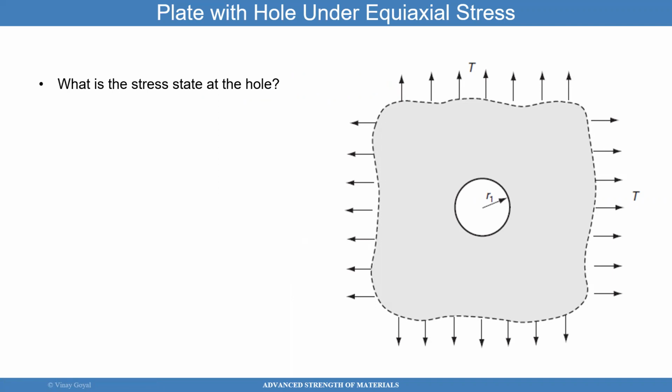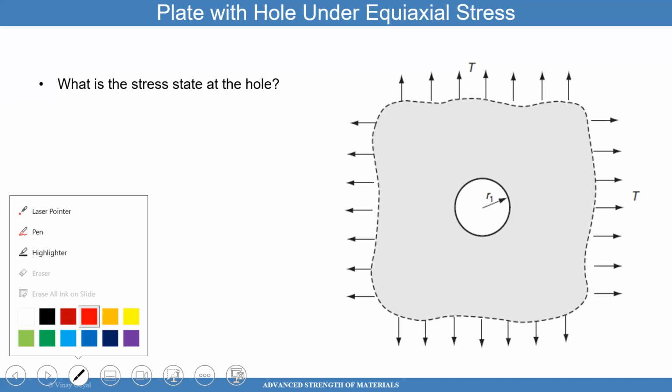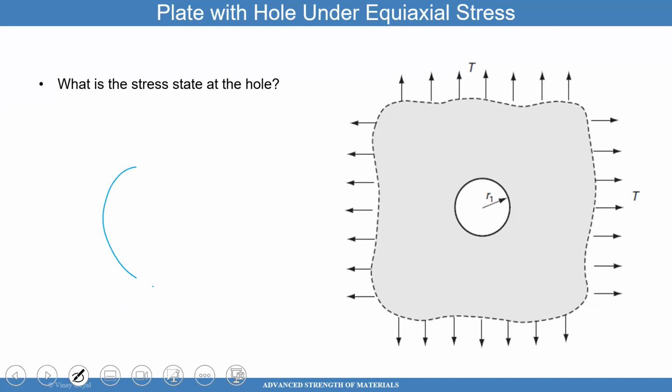And so for that, what we're going to do is something very interesting. We're going to try to take advantage of something that we had discussed before, which is pressure vessels. You can imagine that this could be treated like a pressure vessel with a very small hole where this radius here, or this distance d, goes to infinity.